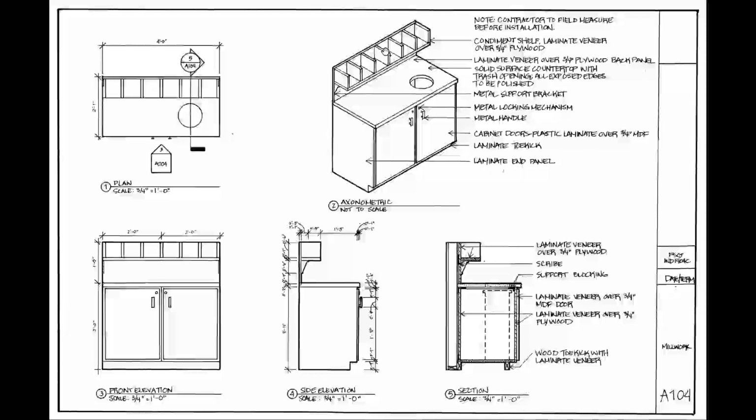Okay, so now that we understand a little bit of the line work here, I would like now to pull apart some of these dimension lines. So the most important thing with dimension lines is clarity and reduction of any type of visual clutter. So you can see here that I'm trying to get the notes as close to the object as possible so that I don't have extra space being taken up by this extra line work here.